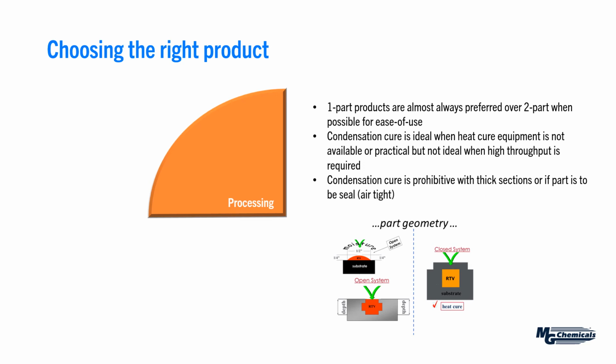One of the byproducts, for example, is acetic acid. So it's not recommended, if the adhesive would be applied onto a metallic surface, that you would choose a material that has acetic acid as one of its byproducts. You would choose something that releases something far more neutral, like alcohol, for example.